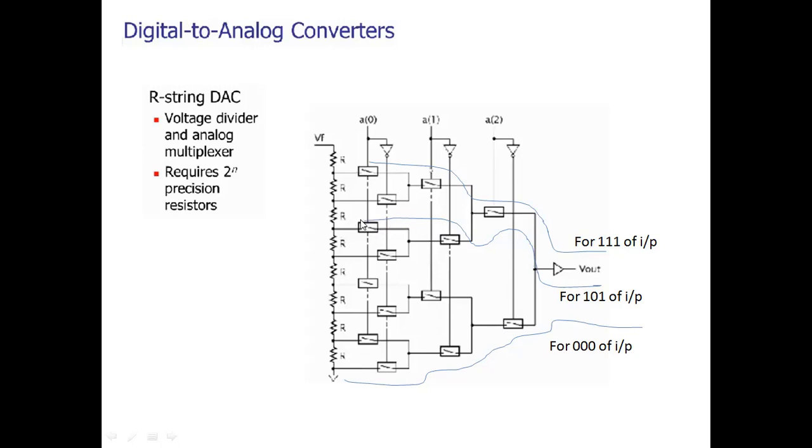So hence we have the conduction path from this switch, and via this particular switch. Why? Because here EF2 is equal to 1. So for a higher value of input, if any input line is high, the upper switch will be activated, and for any input line being low, the lower switch will be activated. Here, as EF2 is equal to 1, this switch will be activated. Hence, this switch, and this. So we have a conduction path here leading to the output B out.